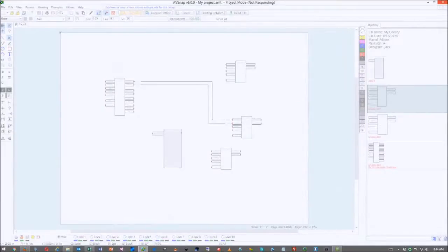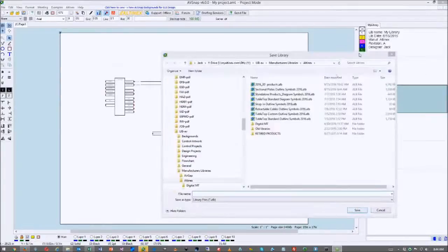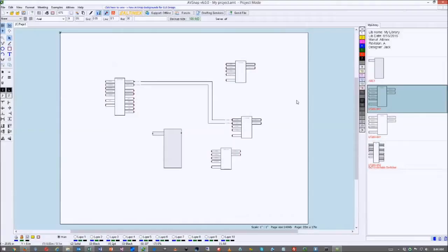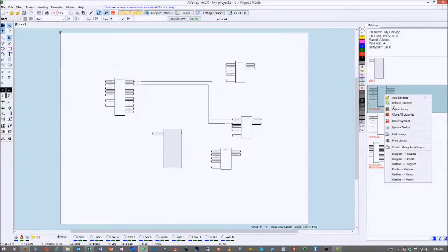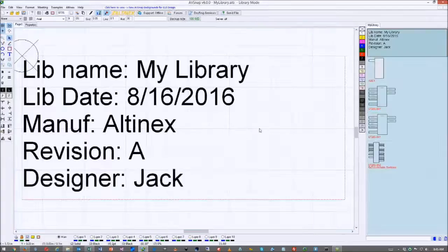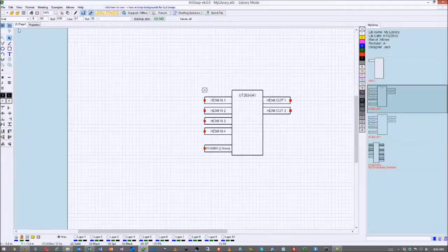So hey, right Jack, now it's just, yes. I'm sorry, this is James. I have a follow-up from last week. We were talking about that pound J. I was playing with it earlier, and I think I figured it out. If you put a text box in the library on the symbol itself above it, and put that pound J, when you drag it in there, it actually shows that designator. I tried adding it on the page and didn't get any luck, but if I added it in the symbol and drag it in, then it would show.